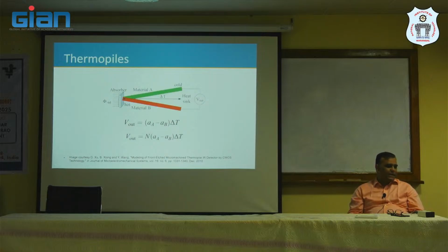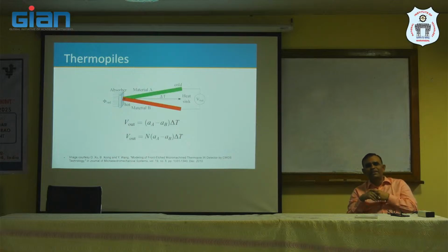Okay. Now generally the voltage produced by just one thermopile is quite small. So whenever you have one sensor producing a small response, there are 2 or 3 things which you can do. You can either put an amplifier after that, or you can try to increase the amount of response by putting sensors in series.